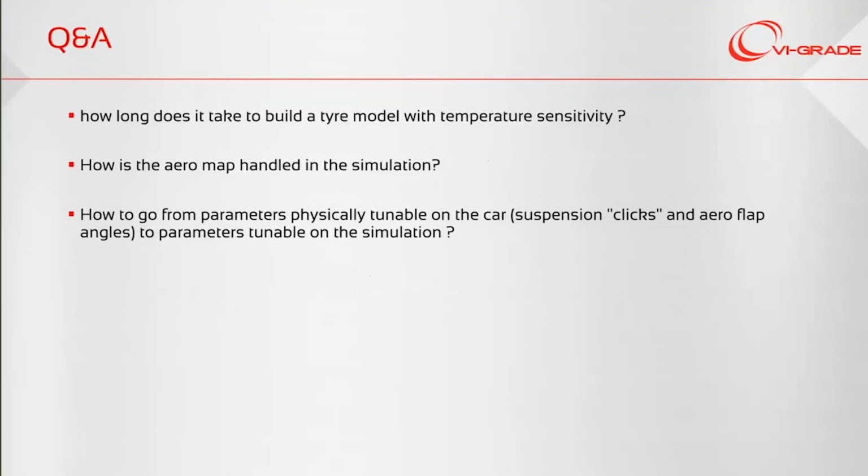Yeah, thank you for the question. I think the answer has to be split in two different areas. For the pure temperature parameterization, we usually use 2 or 3 weeks at our tire lab to develop the thermal parameters identification, thanks to specific certified methodologies, and to get information about footprints and strain energy loss. Then we have to plan a specific outdoor test session with our partner in order to calibrate the model.